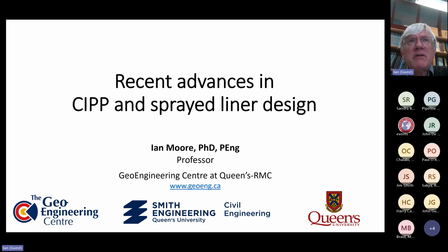The assumption in the work that we've done to date is that the slip between the liner and the host pipe does not propagate past the next set of joints. So if we're looking at a specific joint, there can be extrusion of some of that resin, depending on the liner system, less likely for, say, a fiberglass liner, more likely for a resin impregnated felt liner.